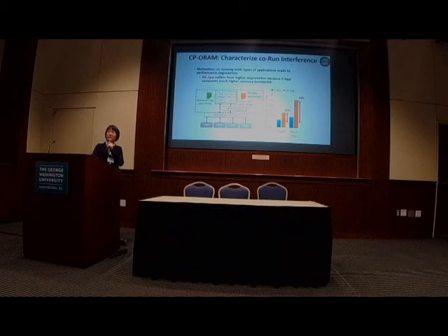This is okay, but the thing is that if you limit the secure application to a single memory channel, then you remove all the parallelism for that secure application. So Path ORAM benefits from being run on multiple channels because of the parallelism you can leverage, because you have so many reads and writes. So once you remove all the parallelism, the performance of the secure application definitely is hit by a lot. Okay, and you may say, can I add more DDR memory channels? But then more memory channels are limited by the CPU pins, because every single parallel memory channel consumes more than 100 pins. So that's very limited by the processor itself.